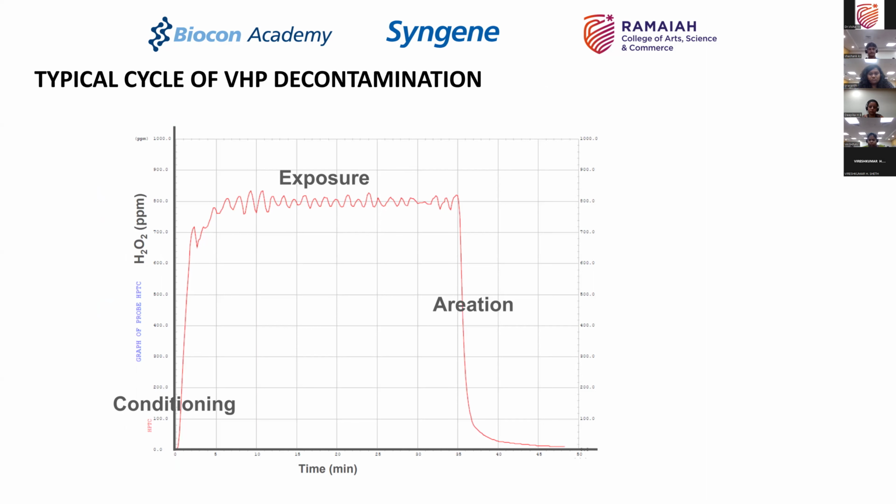Today, with the automation, you have the capability to record the data of the temperature or whatever you are determining, in this case H2O2 ppm, every minute or every 10 seconds, 5 seconds. These are settable on the automation system. So when you see the graph, it will always look like a crazy graph going up and down, a sinusoidal wave, because of the variation within a band.